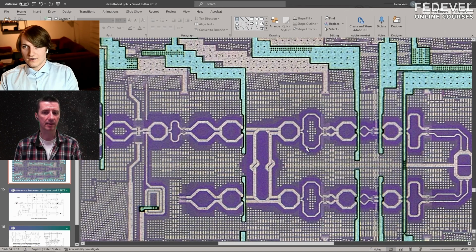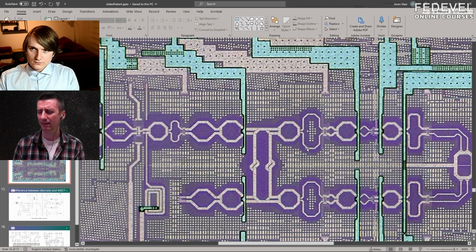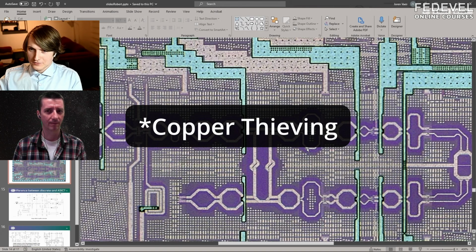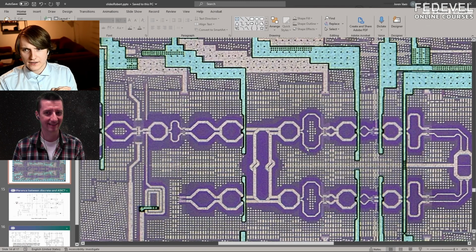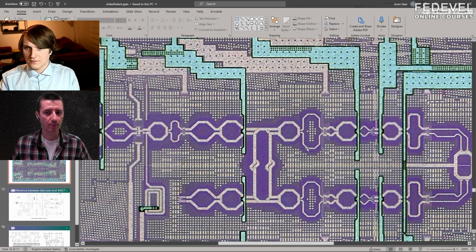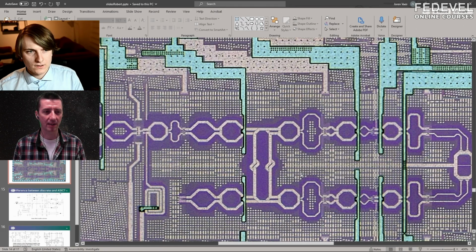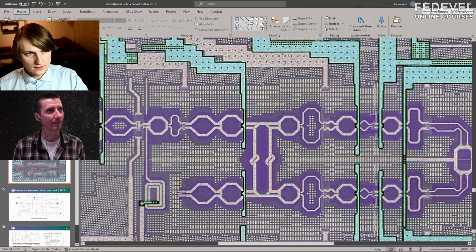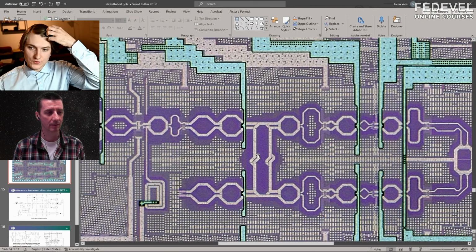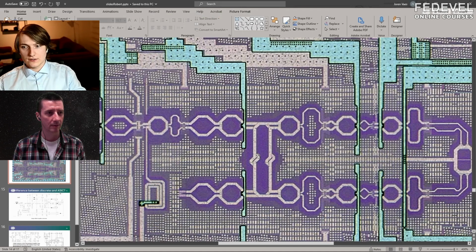Because I think on PCB, sometimes they do it too. I don't know exactly. There is a specific name for this. I forgot how it is called. I don't know how it is in the PCB world. I do know, especially with flex and HDI, I think it is important to have correct metal densities in order to make it. In large PCBs, they usually fill this up because you don't want to bend the PCB, or something similar. And so this is a thing again that the foundry will specify. They will tell you what these densities are.